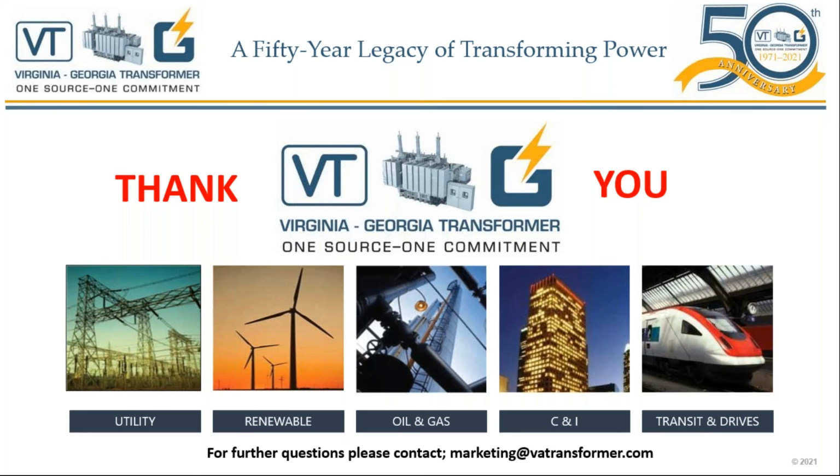This is Parminder. I may add to that. So DGA would show you various activities, heating and also partial discharge. When you measure PD, just measuring the partial discharge will not show other things. DGA alone will tell you what is going on, but PD could be one of the diagnostic tests which you could do if that is the case.